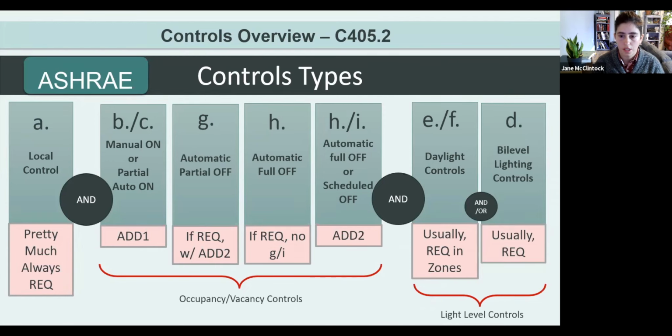So in the 2019 IECC, we see, and we'll look at some examples of this, whereas there's an exception in IECC for light level controls aren't required where there are daylight controls, we sometimes see both bi-level light controls and daylight controls required in ASHRAE. And this is essentially like if your bi-level lighting control is only calling for 50% for your dimmer or such, the daylighting controls aren't allowed to ramp up the lights beyond that point.